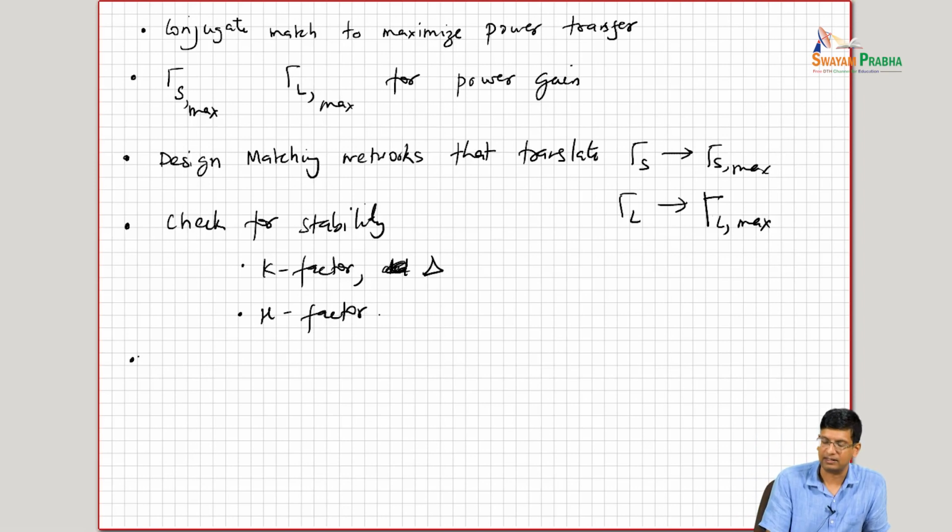However, in integrated design, the one thing is that we have a very large array of devices available. We have a very large array of bias currents, bias points that are available. So the question then becomes, how do I pick my transistor size, how do I pick my transistor bias point such that I maximize the gain, assuming that I do all this? So that's the next step of the process.